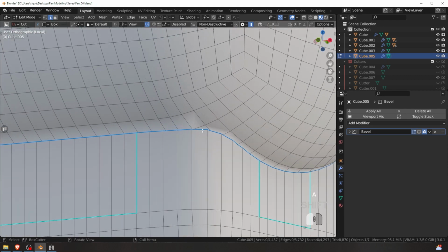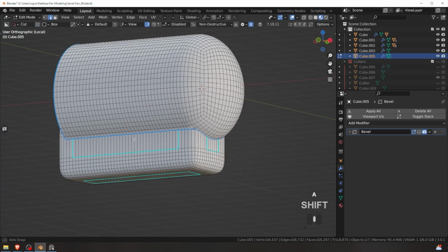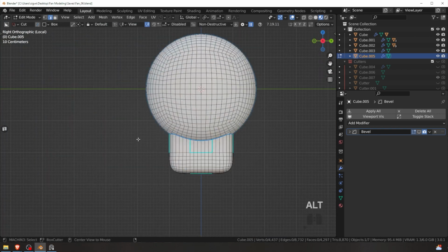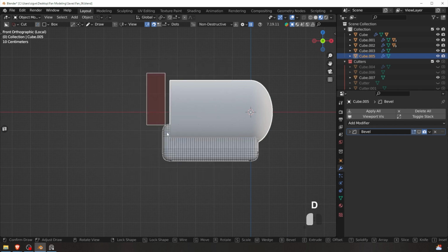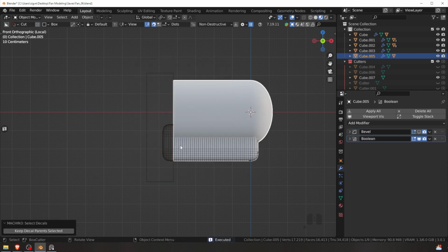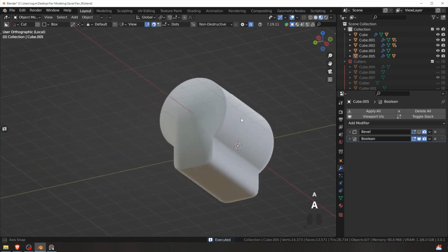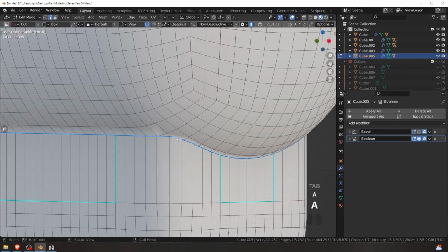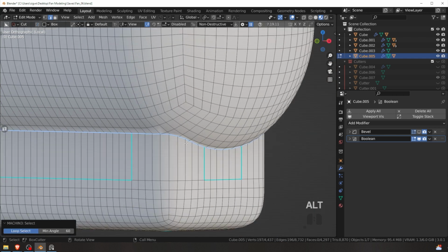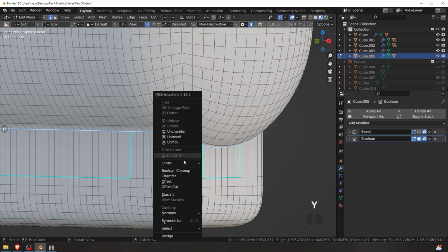You already know it, but we're going to do the other method of just doing it quickly. Actually, before we do that, let me just cut the front as well. So BoxCutter like this, and then just boom, cut the whole thing like that. And for this, let's just go ahead and click 1, then Alt click to select the whole thing, press Y, and then